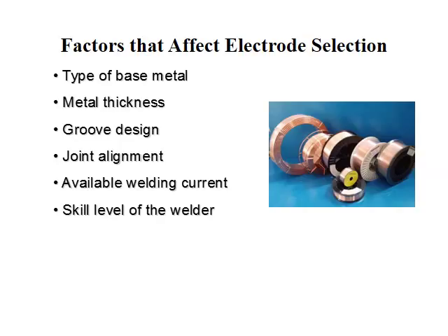Available welding current. How big a power supply do we have? How big a welding electrode can we use? Is this going to be a 4-inch thick weld and we're going to do it in a flat position and just be able to pour the coals to it? Or is it something where we've got a really small power supply and we're going to have to chunk along at a slower rate? So available weld current is another factor that's going to affect electrode selection.